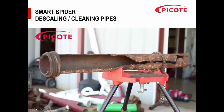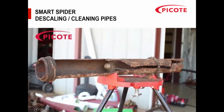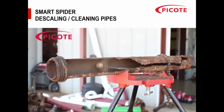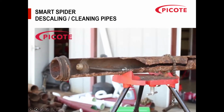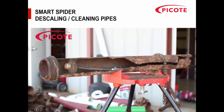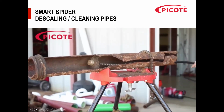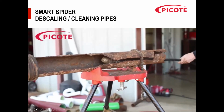Little video here. Now, in normal life, this would be buried. You would struggle to get a jetting machine through here. You'd struggle to get a CCTV camera through there, and you need to be able to camera it so you can select the repair method. The beauty of our machine is that we've got the legs on there, and it goes through. You can see the outer casing behind. If you tape your CCTV camera onto the back of that, you can go through, descale the pipe, clean the pipe, and also do a full camera survey. So we have contractors who just use the Spider to get cameras through sections where you can't get cameras or jetting machines through.